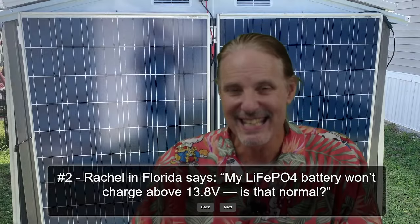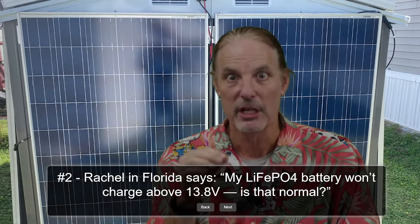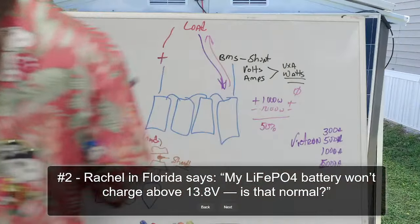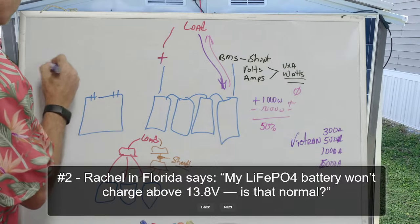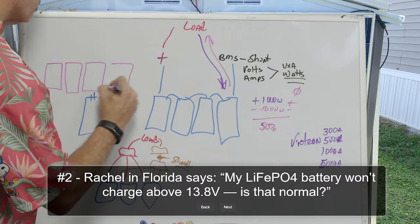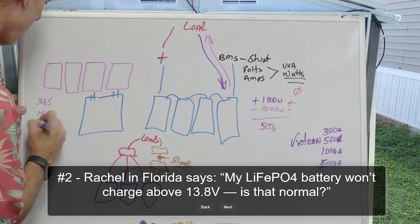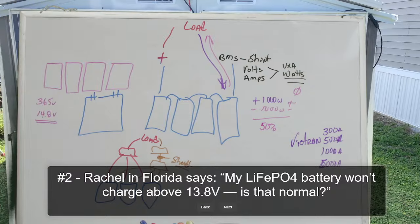is yet again another case of the BMS state of charge being inaccurate. Let me explain what I mean by that. In your case, you have a 12-volt battery, which will have 4 cells, each one of them having a maximum charge of 3.65, bringing you up to 14.8 volts for a full total 100% charged, perfectly balanced battery.